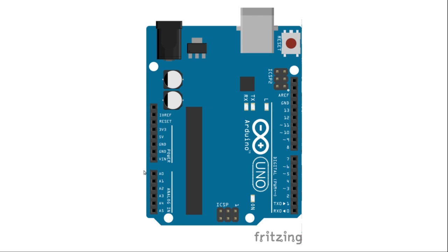Next we have got the analog inputs. There we have got 6 analog inputs. This is an advantage over a Raspberry Pi, where you need an analog to digital converter for reading data from sensors. Of course, I mean analog sensors.